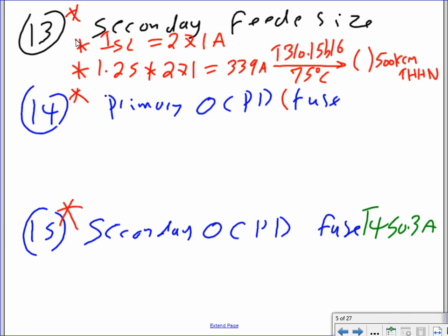So we're going to carry how many conductors? 4. Why 4? Phase A, phase B, phase C, that's 3, and a neutral, because it's a Y. Could I have derated the neutral like you guys are going to be doing with me? Yes. For the sake of this calculation, we don't want to complicate it and start derating the neutral at this time. Okay.